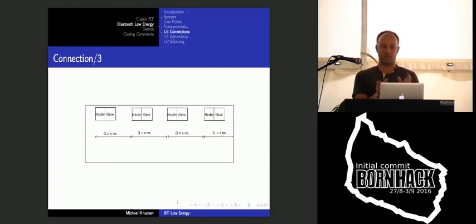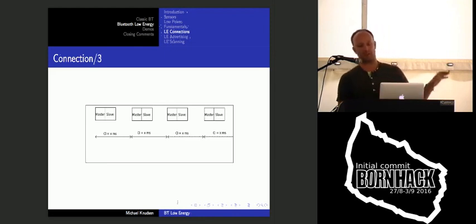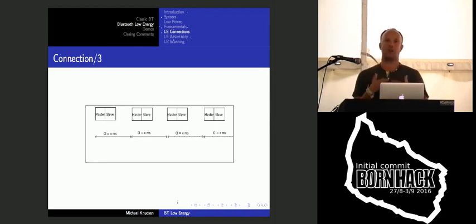In these two slots, the device gets to hear whether the other guy's there. For instance, if the master is doing something else, the slave can hear that the master wasn't there, so he can just go back to sleep and wait for the next connection event. Similarly, if the master doesn't get an acknowledgement after his transmission, where the slave is supposed to acknowledge and send back some data, he knows the slave isn't around, so he can turn off his receiver early.